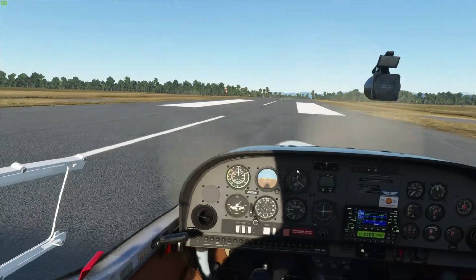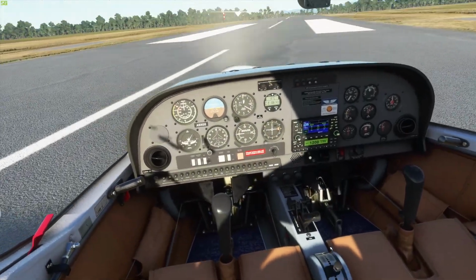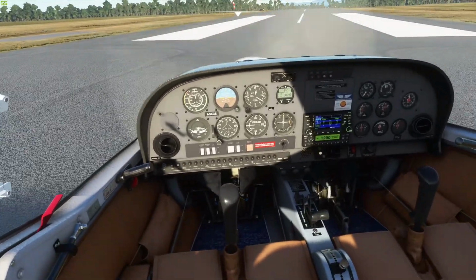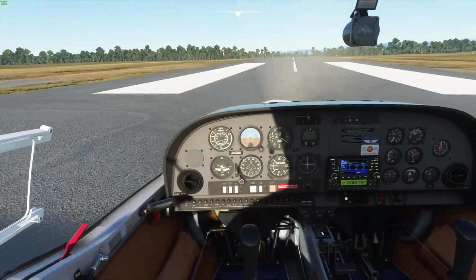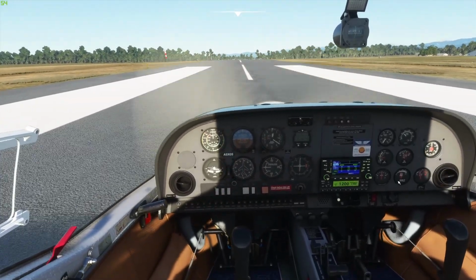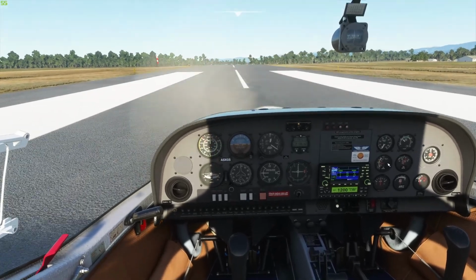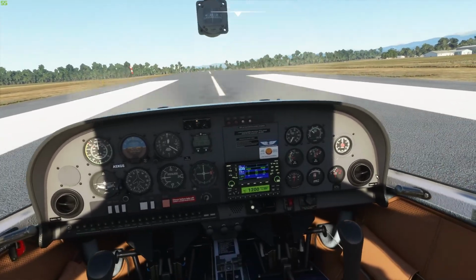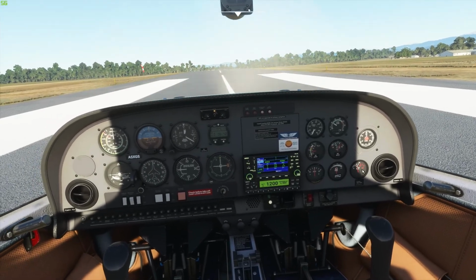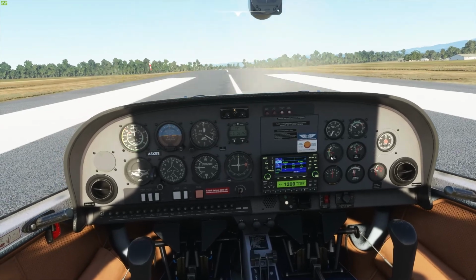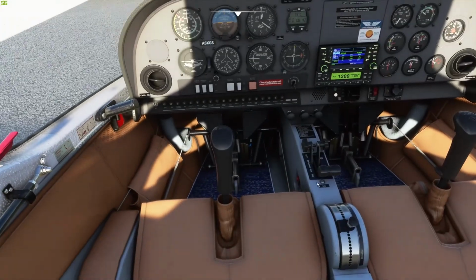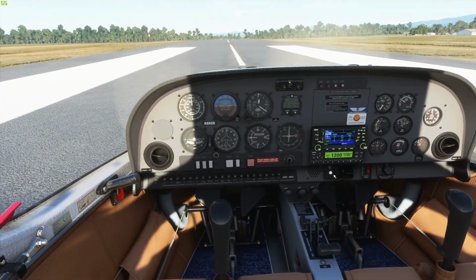And we'll quickly do some pre-takeoff checks here. So the trim's set. I don't know where the takeoff position is, so we'll say it's about in the middle. Throttle friction, don't seem to have one of those. Mixture, we don't have one of those. Instruments, yeah, instruments are checked, so the oil temperature is very high. So that's one to note. We'll keep an eye on that. Coolant temperature is fine. Oil pressure is the main one though, that's all good. Ignition's on both. We've got fuel cocks on, and the flaps are set for takeoff.